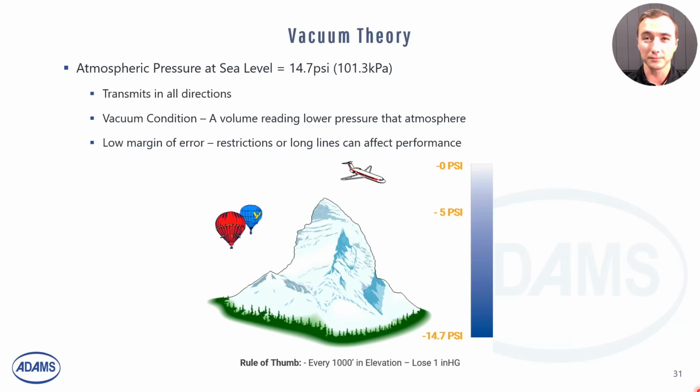While that suction, that flow, we'll call it, while that's part of the process, that's not the whole story. There's actually a lot more going on behind the scenes here to handle parts. And with that is the idea of atmospheric pressure. So atmospheric pressure is the pressure all around us. It's transmitting in all directions and always present. At sea level, it's going to be equal to 14.7 psi.